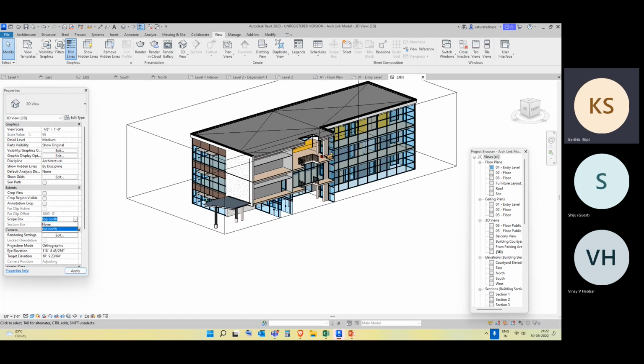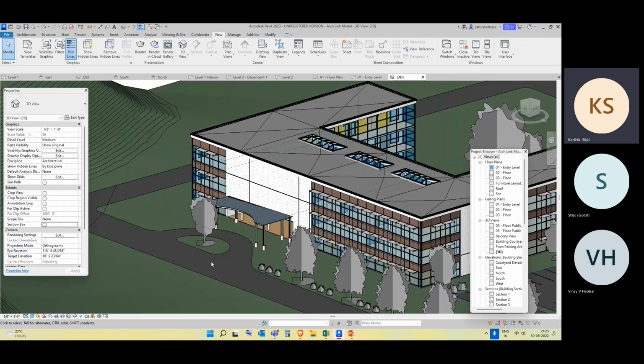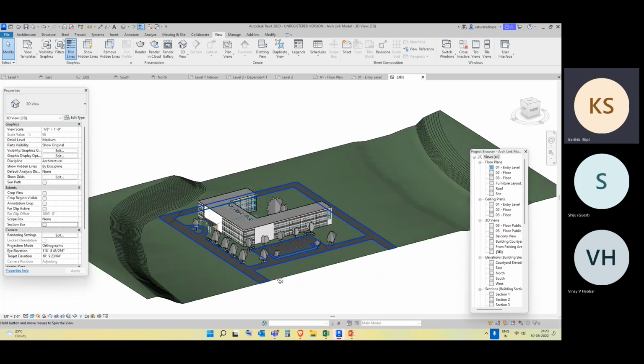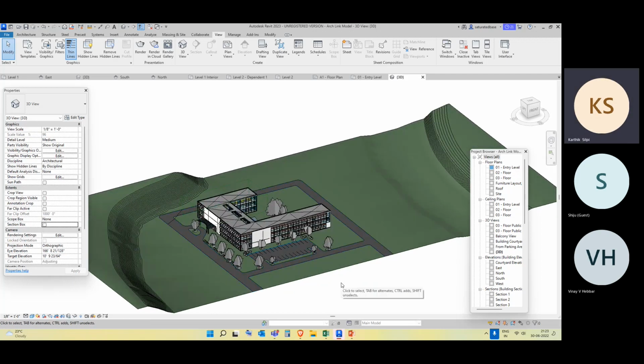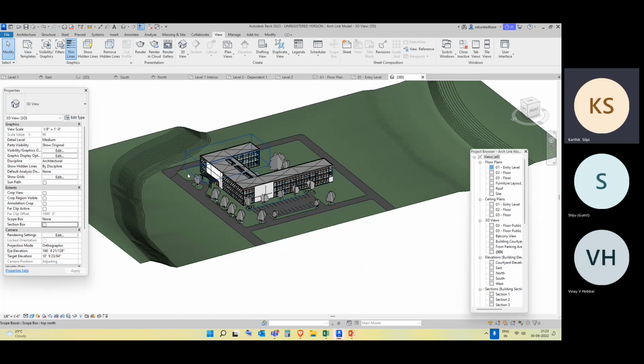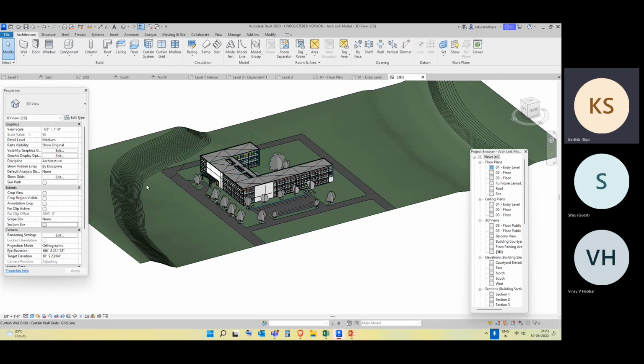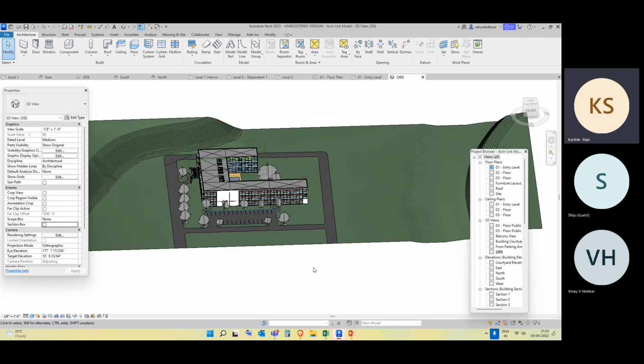But normally what happens is you will not have access to the whole model. Here I'm showing with the whole model. If you do not have permission for the whole model, you cannot select none here or uncheck the selection box. That will be locked by the managers with permissions. We are not going there, because we are learning in simpler terms with one person operation. But in Revit, multiple person operation is also possible, and the manager can restrict what we can and cannot do with the permissions.